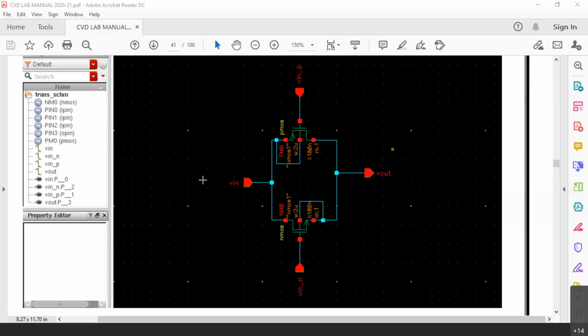Now, if a transmission gate cannot be used as a buffer, what is its use? Because simply input is coming to the output. If a weak input is there, that will remain weak even at the output. Only thing is, logic 1 will pass through Pmos, logic 0 will pass through Nmos, that's all. Otherwise, the signal's power will remain the same here, because there is no power supply at all in this transmission gate. So what may be its use now? Any answer?